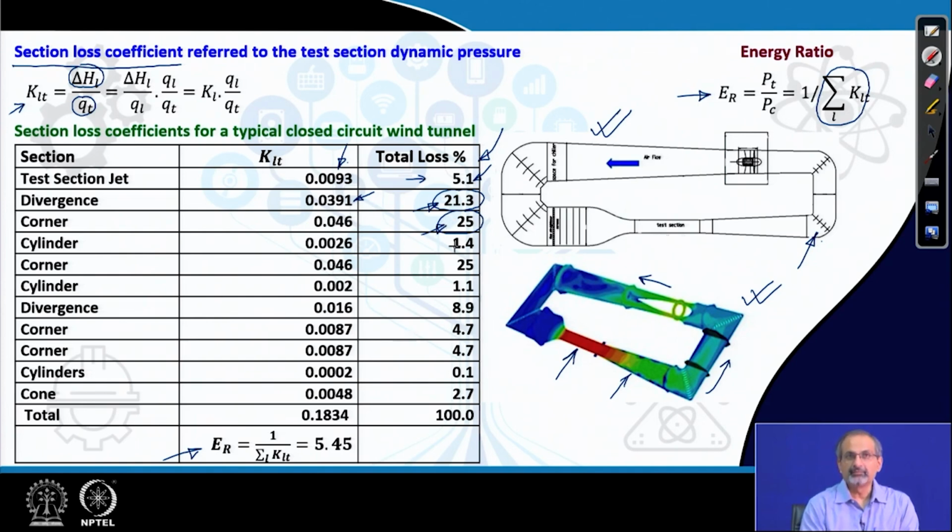So, the flow is still at a fairly high velocity, and incidentally the losses being incurred are also on the higher side. Of course, as you move through the diffuser, the losses are in general higher because the flow is going through an adverse pressure gradient, and there is always a tendency of minor flow separation occurring as the flow moves through such an adverse pressure gradient.